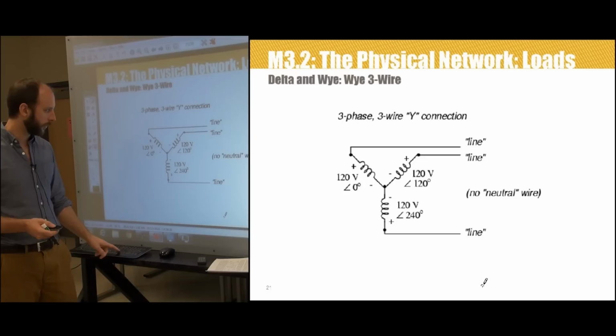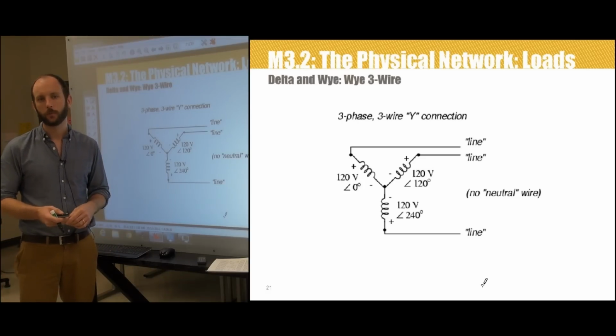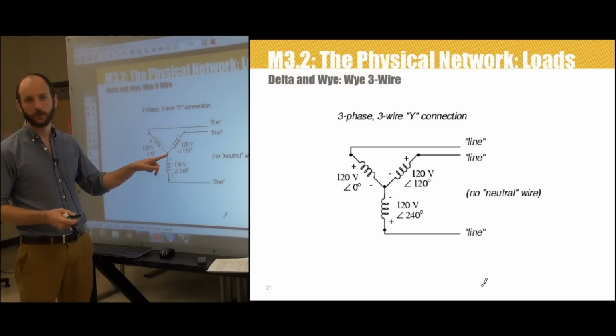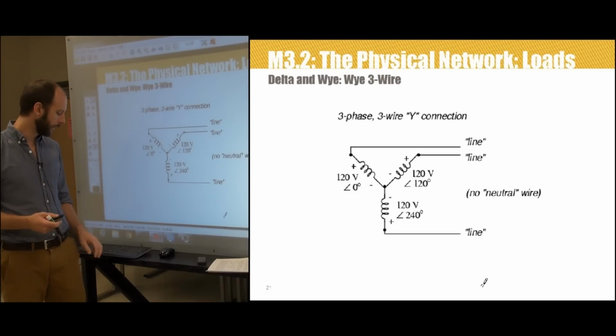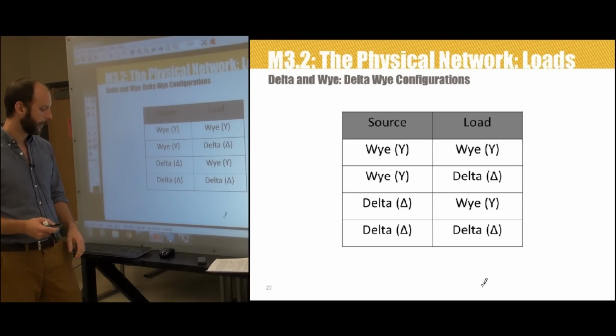The Y configuration, in contrast, is normally grounded at this center point. It's pretty common to go ahead and ground that. Here, a single ground anywhere else in the system will immediately cause a fault.